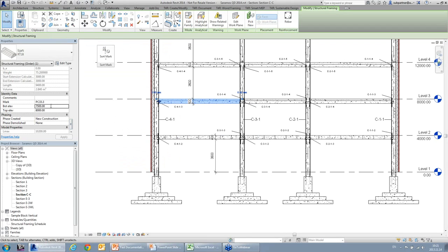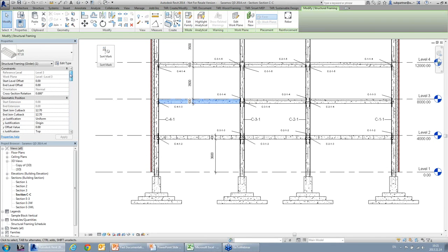It's very handy because right now we have top and bottom elevation values, and those values go from the zero point of the project. Because like you see, for the beams with regular Revit, we can't get the real elevation. We can just see the level where the beam is located, but we can't get the real elevation from the zero point. Right now we did this for the project elevation values, but at the same time we can do that for the shared elevations.